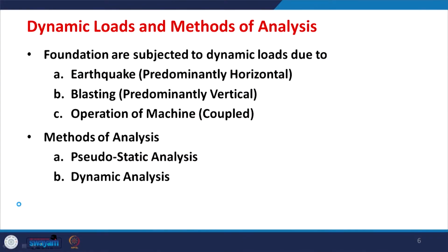When we talk about dynamic loads, you may be aware that foundations are subjected to dynamic loads due to many reasons. One of the reasons is earthquake or seismic loading. When we talk about earthquake, we apply the lateral load, that is the basic difference. When you do not consider the earthquake, vertical load will be always acting, but it is the lateral load which is a must to consider during the earthquake. Suppose if we say we are considering the earthquake load and then only we consider the vertical load, so that will not be a fair thing. So, the lateral load or horizontal load, that is predominantly important for earthquake loads.